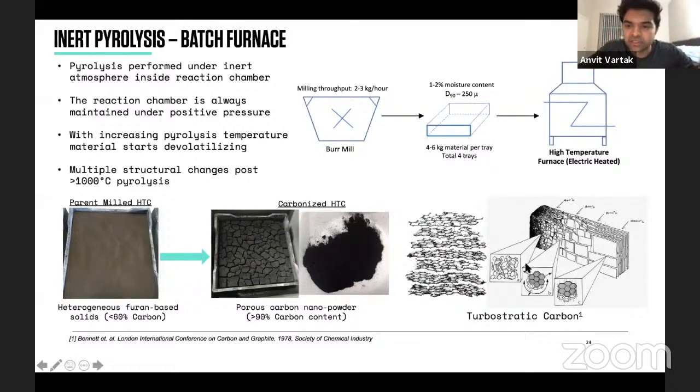But as you start heat treating it, taking the temperature higher and higher, when you get to 800 C, it starts forming itself a little bit, because it starts losing all those functional groups that were giving it hindrance to make this nice plane of sheets of carbon.